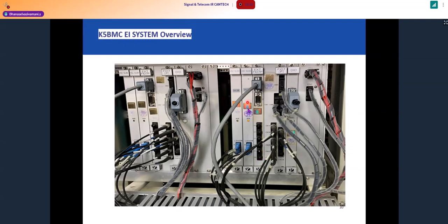And similarly, HSC sub also has the fiber optical communication connections for logic subrack to logic subrack. These FIO 7P ports are made with the FC connector multi-mode cable. FC multi-mode cable will be used, FC to FC. And when it comes to the HSC sub, we'll be using ST single mode connection. We are using it for the data logger purpose.